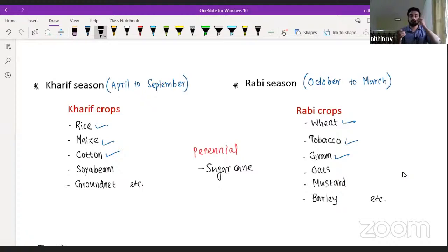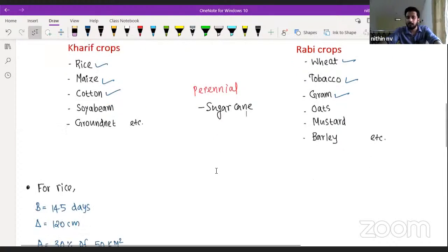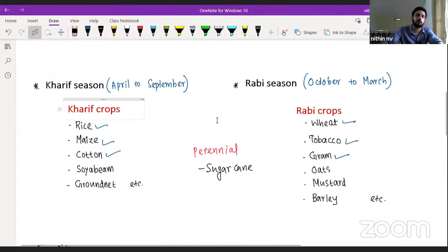Which of these two values is more, or maximum? That maximum value will be our minimum discharge value. Similar to what we have discussed, the length of transition curve in transportation engineering, or in RCC you will study maximum spacing is equal to minimum of some values, like that. So similarly, we will check what is the discharge required in Kharif season. We will check what is the discharge required in Rabi season. Whichever is maximum, that maximum value will be our minimum design discharge in the canal.